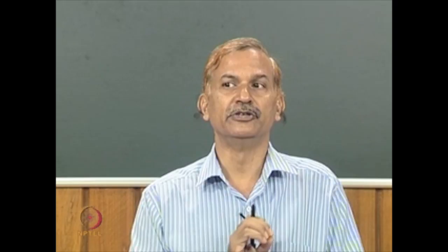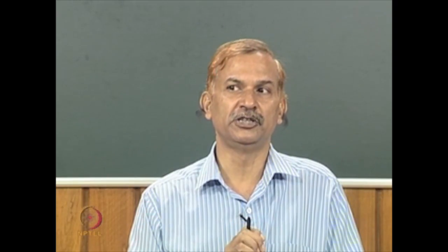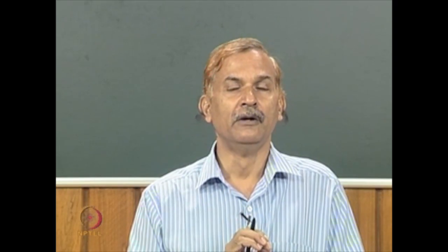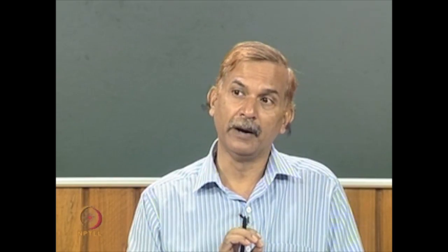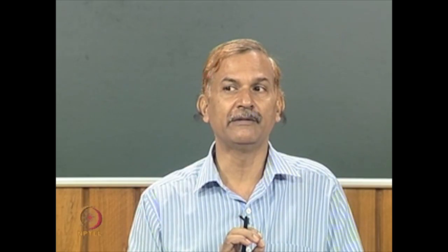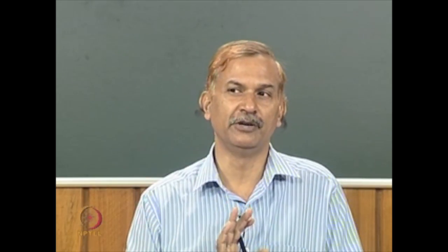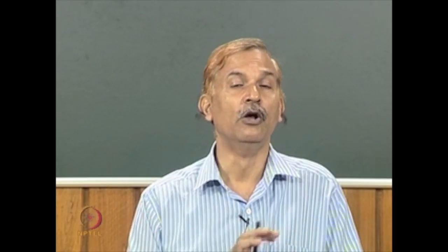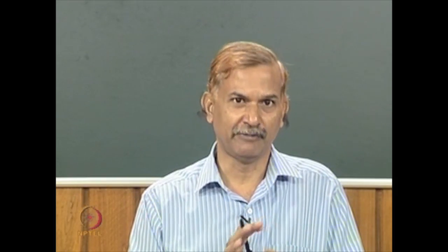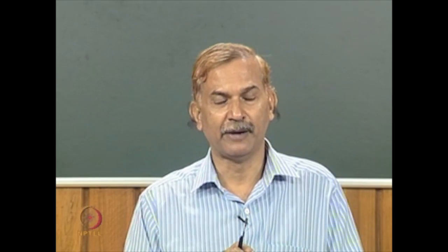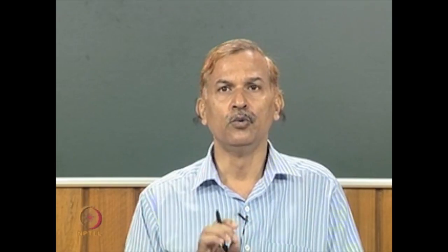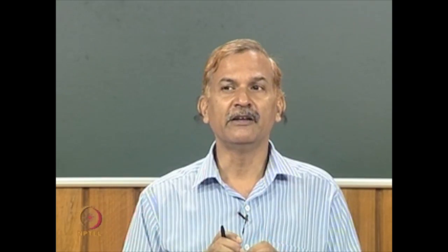Since it is a hard problem, currently we are using some heuristics, and with the help of these heuristic methods, we try to find some variable ordering which gives us a compact representation. The BDD that we get may not be the minimal one, but it is going to give us a compact representation. So, we apply some heuristic to find a variable ordering, and after that we apply this variable ordering to construct the BDD, and in most cases we have found that we get a reasonably good size of BDD representation of any function.